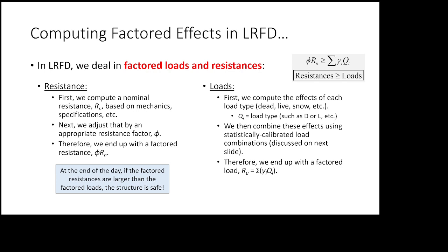Take the table, it snaps in half at 800 pounds. With me so far? Now, instead of just using a factor of safety of 2, what we might use is a resistance factor. We use the Greek letter phi for that. And so we might use a resistance factor of, I don't know, 0.8. These are lookup values. We use different resistance factors for different limit states. That's something we're going to be introduced to a little bit later.